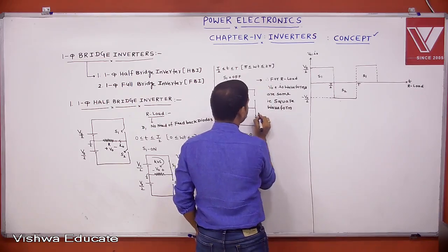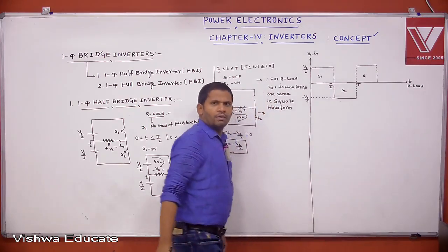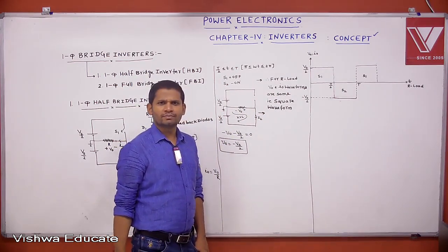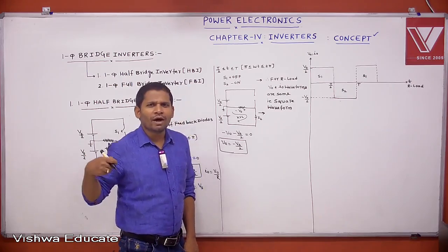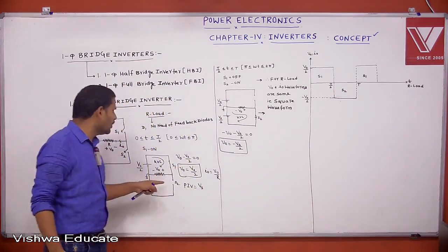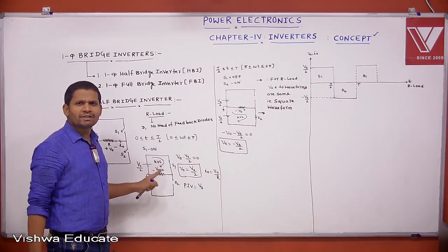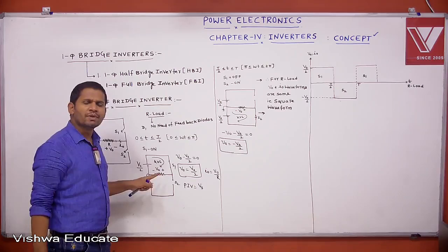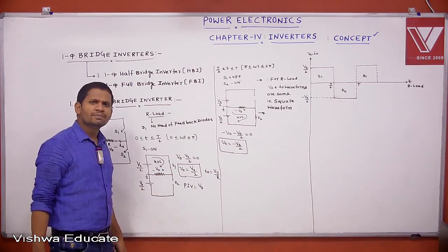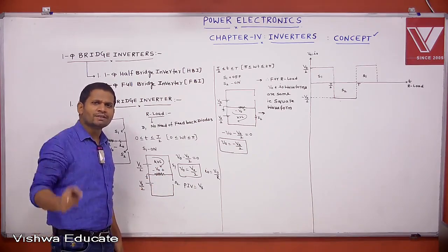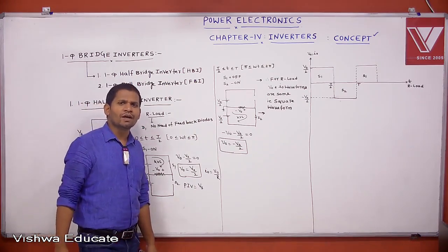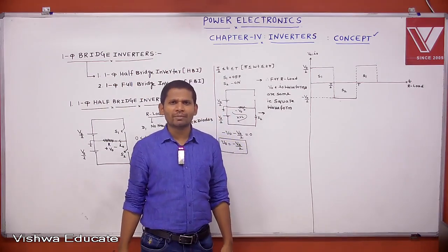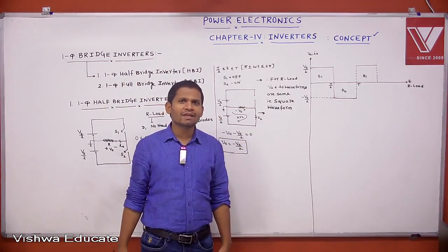We know that in a voltage source inverter, whatever the load you connect here, which waveform remains constant? The V0 waveform remains the same. Then which waveform will be changing? That is the difference I discussed. In a voltage source inverter, output voltage waveform and amplitude are independent of load parameters, but output current depends on load parameters.